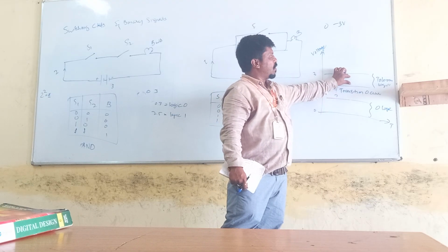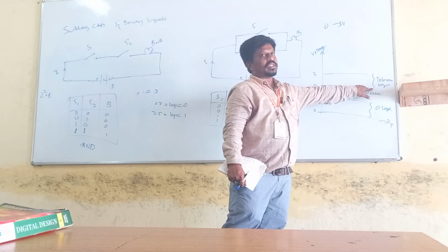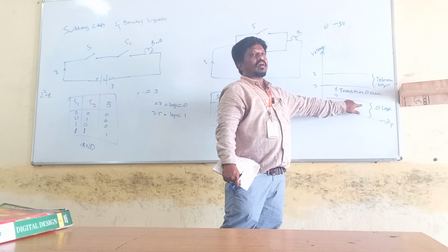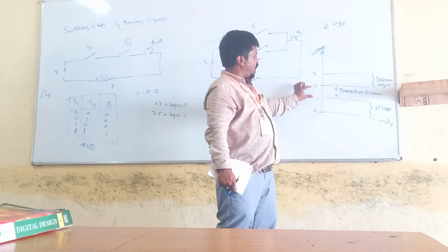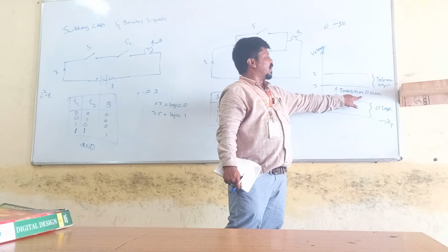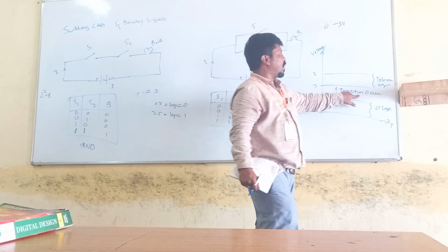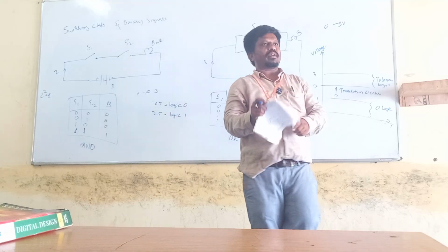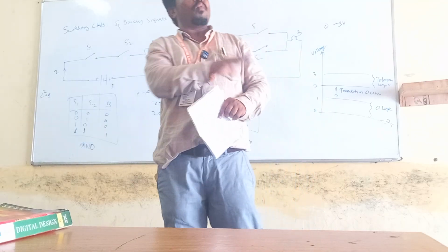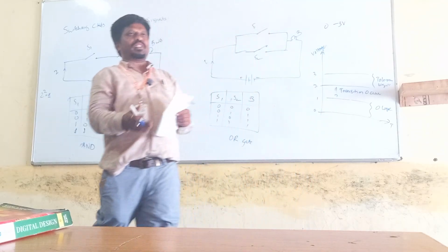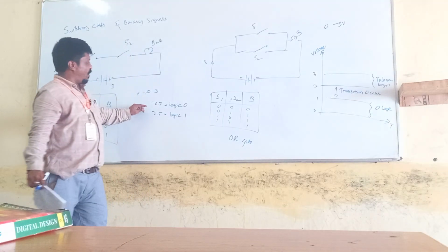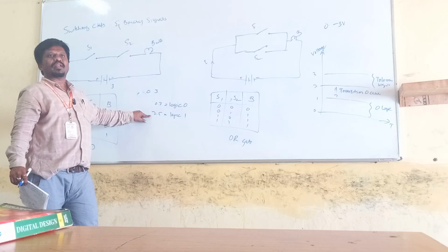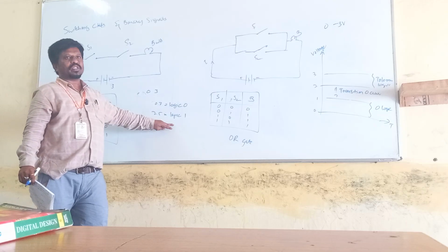This period is the logic tolerance period for logic 1. This period from 0 to 1 is the tolerance for logic 0. This period between 1 to 2 is considered where the transition occurs. This tolerance period is considered the transition period. It has to switch from 0 to 1, 1 to 0. If my voltage is around 2.5 volts, then I would definitely have to use logic 1.